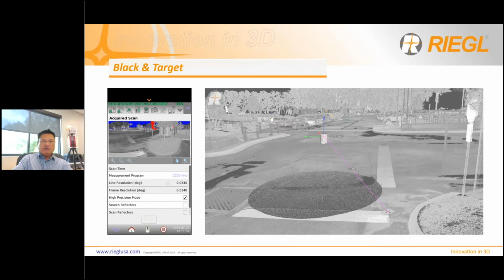now, I don't just recommend ground, right? If you have a project, I would put them on some flat vertical surfaces and shoot them in with a total station or something. But I don't have the luxury, so I use all ground. Yeah, you can see here the target, the scanner is put next to the ground. And when I scanned it, there's a 2D view. I can visualize it. I can see that my target's in there.